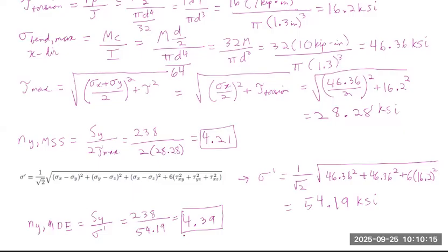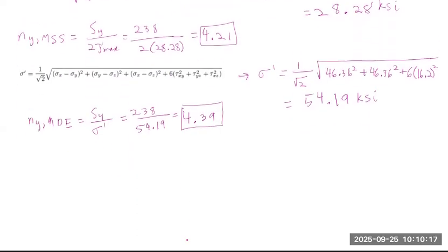Okay. Now let's consider for point C the right surface of the z negative face. So this is the face that looks like this here. And on this face, there is only going to be shear stress because it's located on the neutral axis.